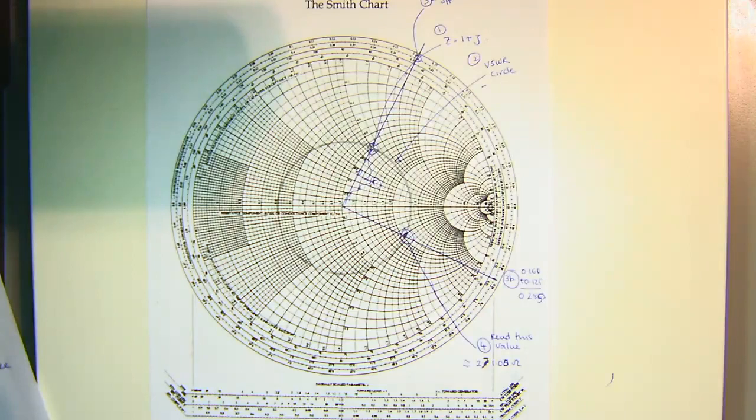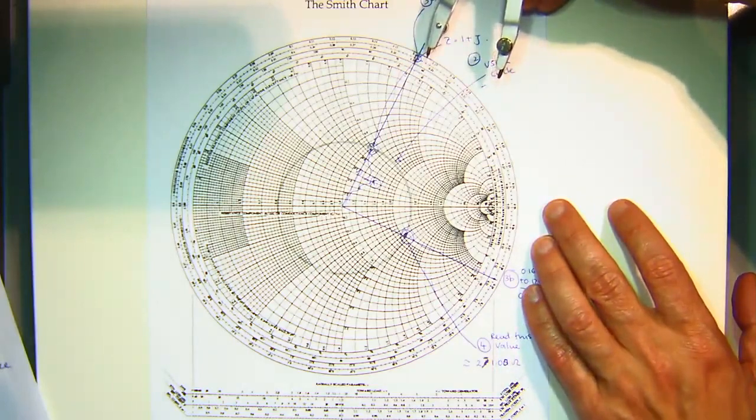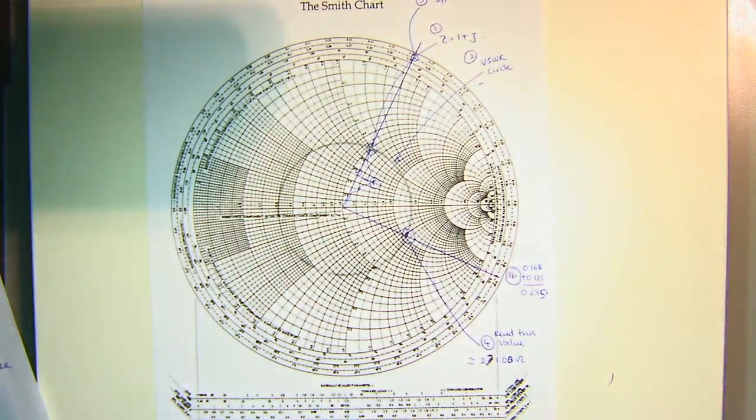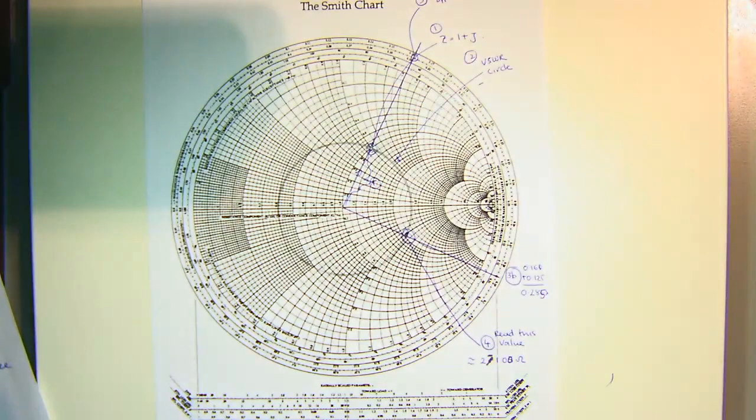Then what we said was, I wanted essentially to work out what the impedance is going to look like if I'm connected through this transmission line of lambda on 8. So we want to know what the impedance looks like if I'm going towards the generator. Sorry, I had it here and I rubbed it off. If I'm going towards the generator, what's the input impedance going to look like? So essentially, I've got to calculate what lambda on 8 is. Lambda on 8 is 0.125 lambda.